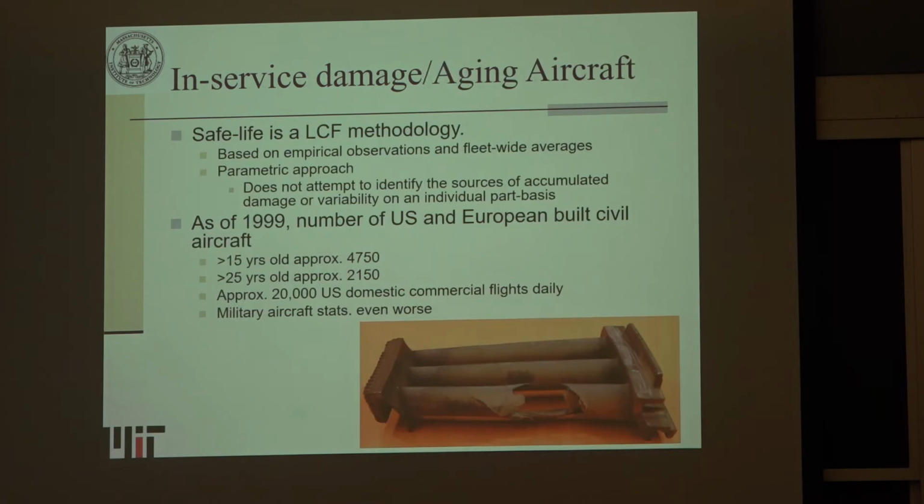And what you'll see is this was actually taken out of an operating plane. What happened here is the thermal barrier coating wore away, and a mechanism called sulfidation occurred. This was related to the crude.